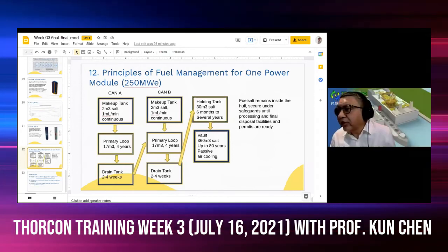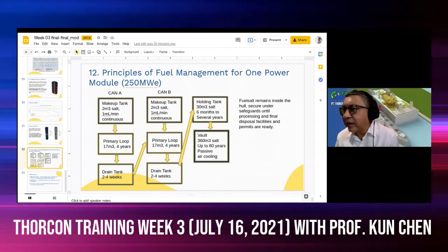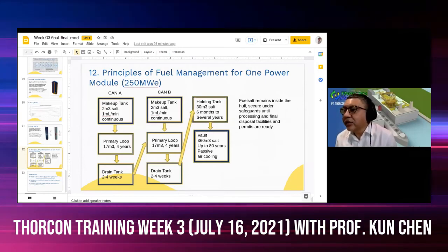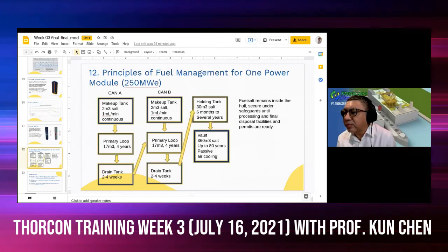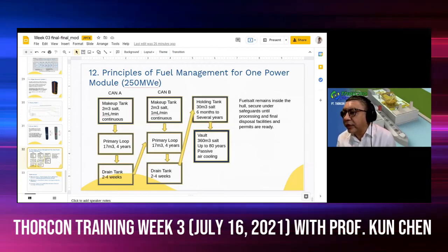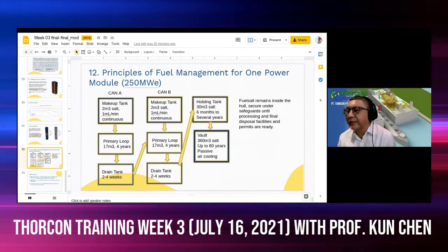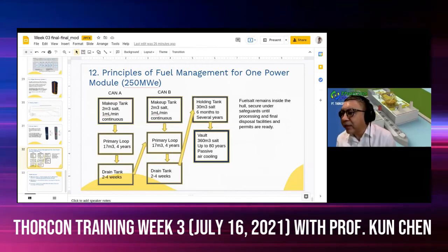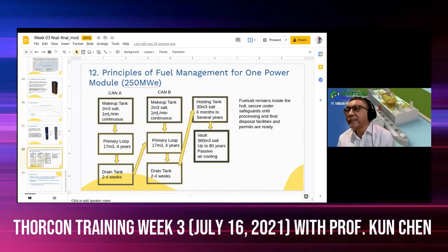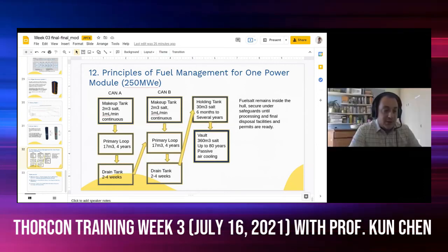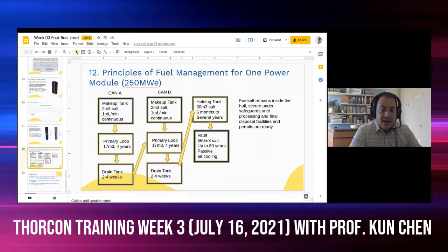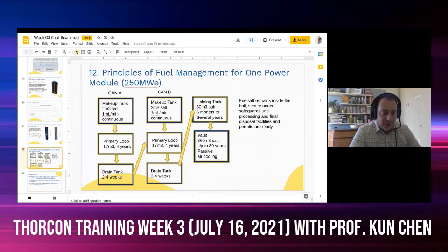All right, so there's a question from Professor Waris from ITB. And the last question: in the fuel cell matrix, the volume of the graphite is much, much bigger than the fuel salt, so the moderation becomes much higher. What is the impact on the fuel breeding? Manu? The ThorCon reactor has a very good neutron economy and a rather large conversion ratio.